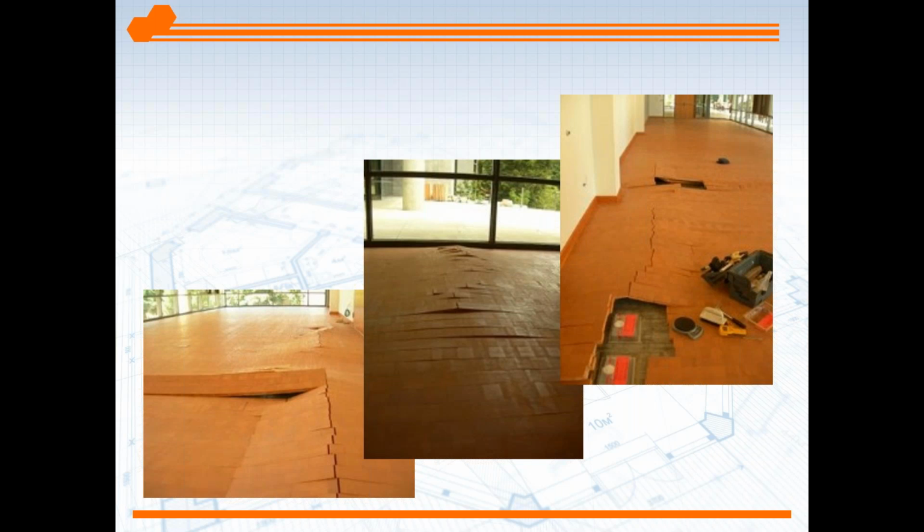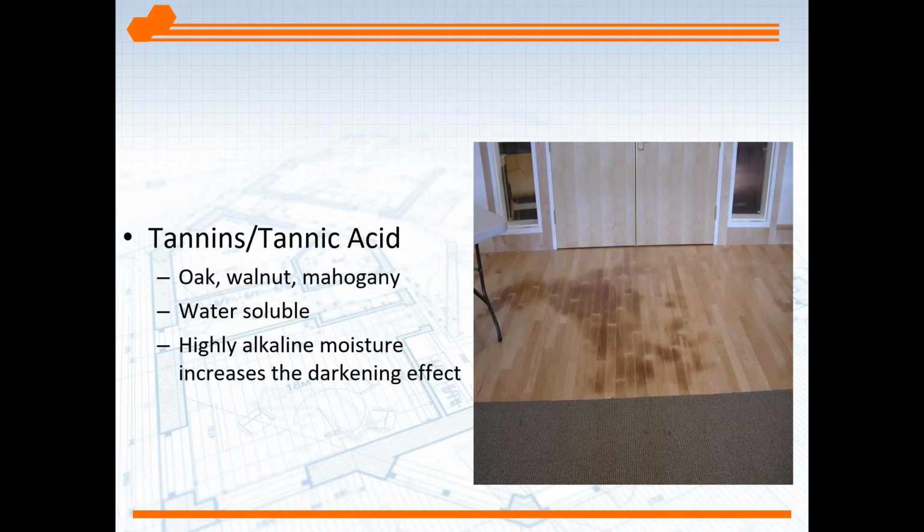There are different causes to get here, for example when it's over new concrete, there's moisture in the concrete. But I think the most important takeaway from these three pictures is that moisture testing and evaluation of problems should be done before you have a problem, before the floor is installed. Being proactive as opposed to reactive is the best medicine to avoid some of the issues we just saw in those slides.